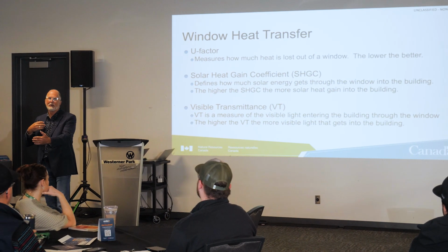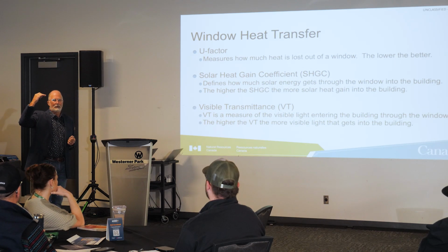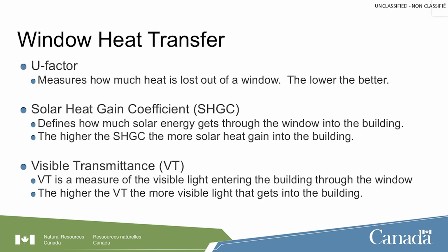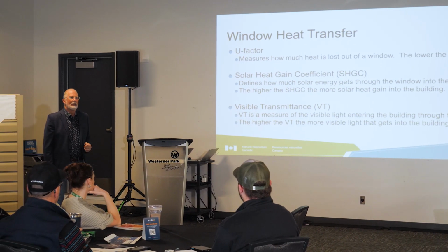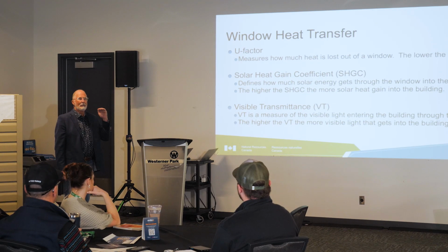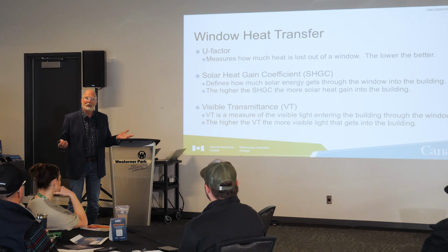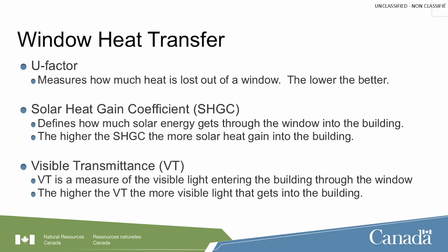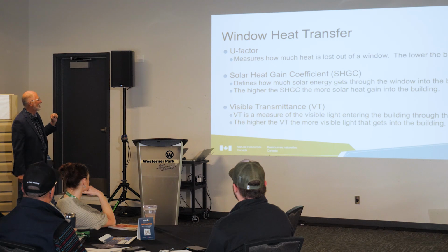But what about reverse that in the wintertime? 0.2, I'm not getting any free heat from the sun. So my energy bill goes up. So understanding that is important. So we learned very early when the new energy code came in back in 2016 that I could really cheat that code by putting in a 0.7 window. Right? I would overheat the house like crazy, but I sure made it easy to achieve compliance with the energy code. So now we have things called peak cooling loads, which really are influenced by the solar heat gain. And you guys can jump in if you're energy modelers, just jump in. If I get something wrong, it's been a long time since I've done a lot of this, but.